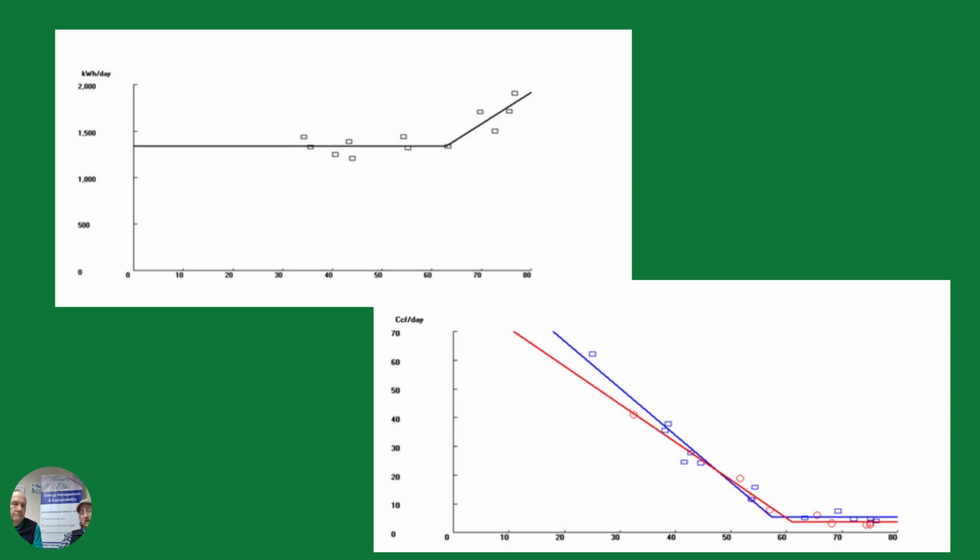And this is probably from a cooling system. And that may be even obvious when you looked at the utility meter, but one of the things that we can start to identify here is how many kilowatt hours are using every single day of every single month of every single year, regardless of weather. Well, in order to really understand that, we need to understand what's happening in the facility and collect nameplate data off of the heating and cooling equipment, fans, pumps, count the lights, etc. But there's a lot of energy being used here all the time.